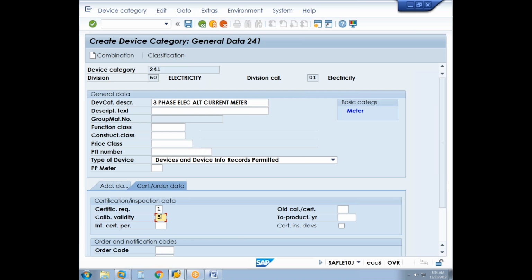So initially when you put it, it is going to work till 2024. Again you have to check it in 2024. If required, you have to recalibrate, or if it is okay, it can continue for another 2 years, 3 years. We extend the date. So this calibration date is very, very important. Unless the meter is certified, it cannot be installed in the system. Once the calibration period is over, it cannot do meter reading. It will show you cannot do meter reading because the calibration is over. It means it has to be replaced with another meter. We can understand it that way.